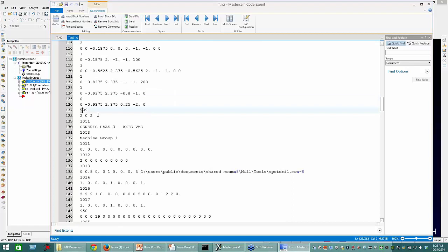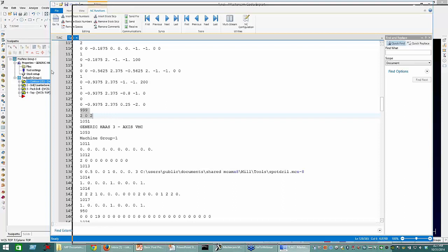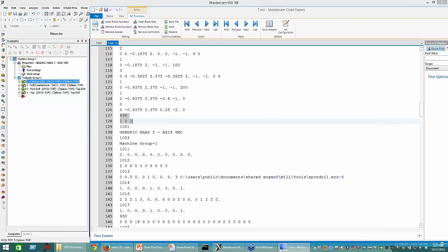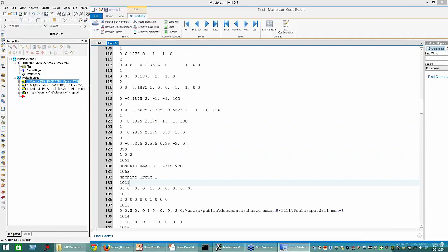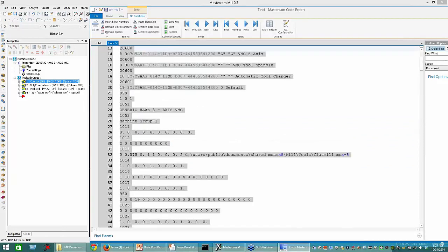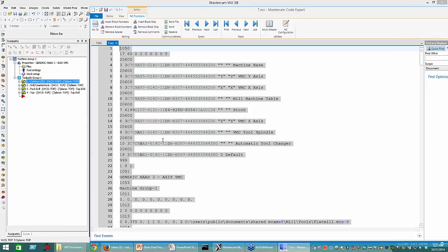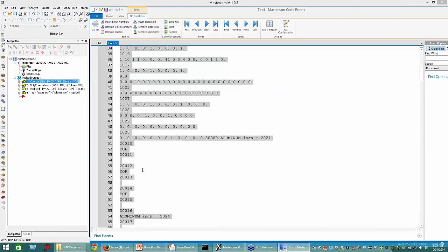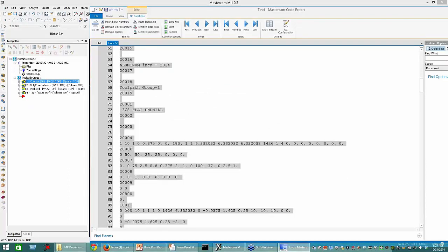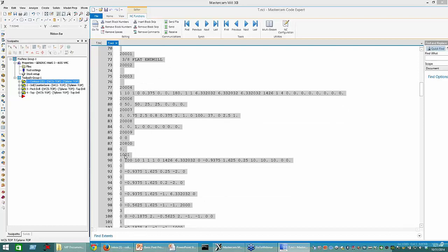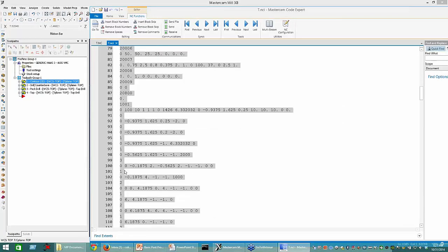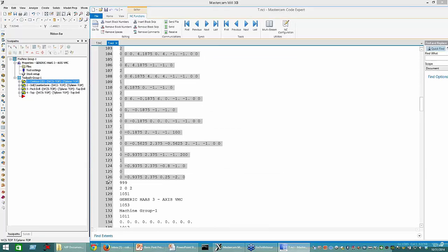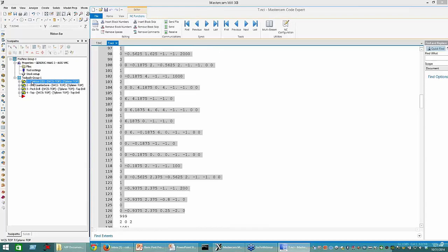And then down here, starting with the NCI 999 line of the next operation, we're now processing essentially the second toolpath in this list. So contour number 1 generated the data starting here all the way up to the top with the 1050 line. So again, if we read down, all of this information here is preparatory information until we get to the 1001 line. So you'll notice there's 88 lines of code ahead of the start of this operation. Then from line 89 down to line ending, this is all the motion data for that contour.